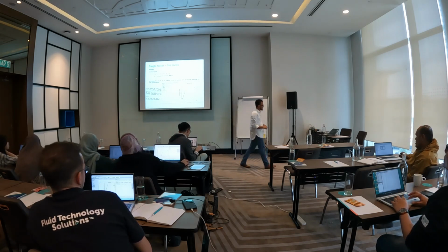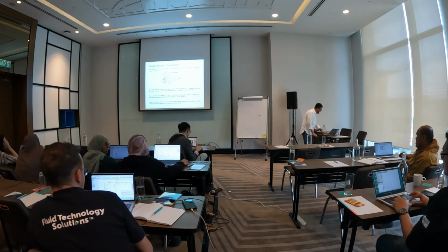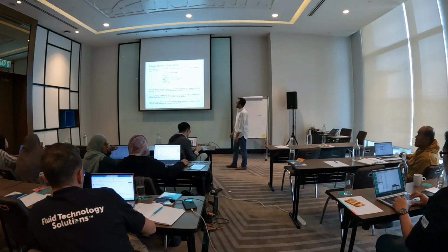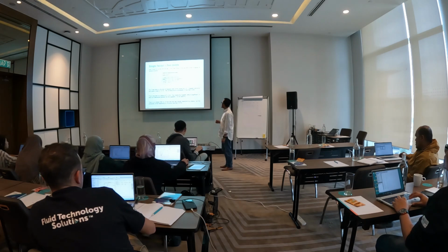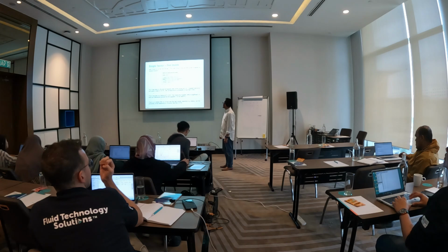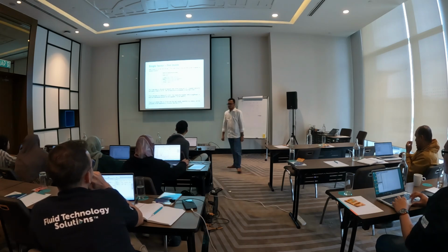So we can see in the analysis, if you see in the ANOVA tab, the next tab after the effect tab, you can see the p-value is less than 0.0001, meaning the model is significant.